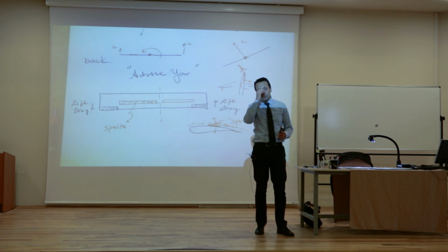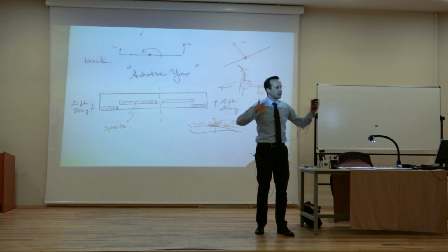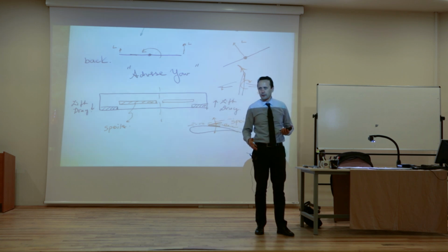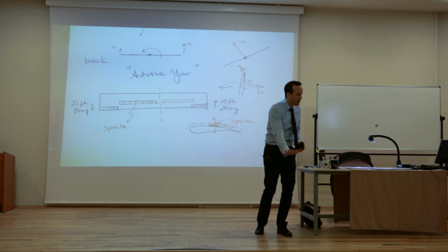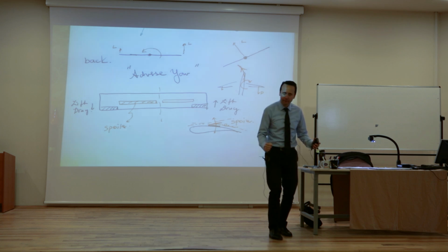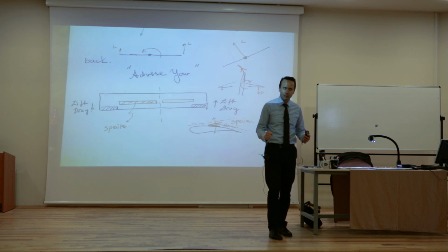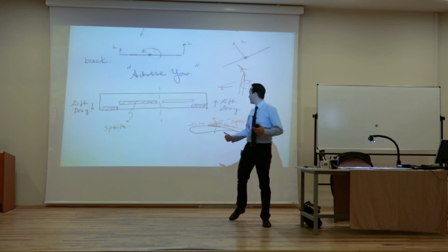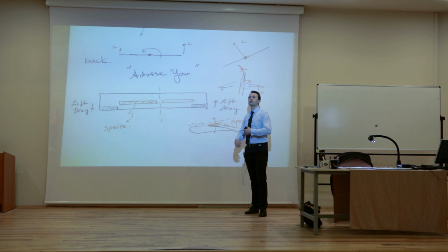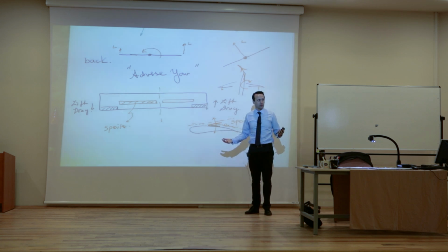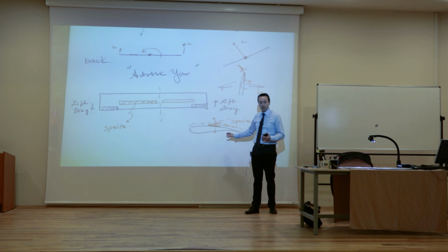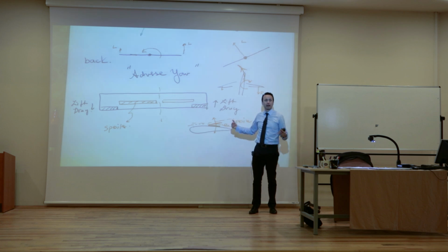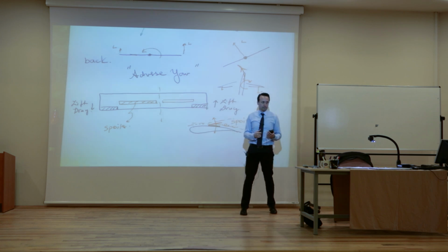So if you have a soft landing that kind of does this, it's not a good thing. You might see, if there's a lot of side wind or a lot of turbulence, bad weather, a good pilot would just smash the airplane on the ground, put the landing gear firmly on the ground, and then go on the ground. So you open up the spoilers, which will remove the lift literally, okay, and at the same time have a lot of drag to slow you down. Is that good?